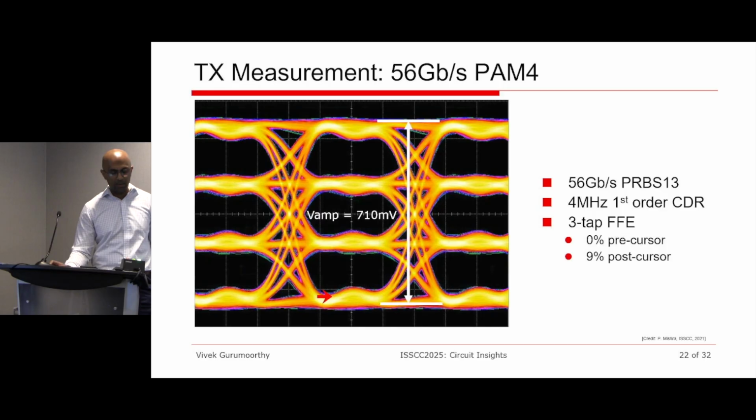So this is where the different levels come into the picture, right? So this is PAM4. So this is the -3, -1, +1, +3. And the way to visualize it is, let's say this is 710 millivolts, right? And you have 127 levels out of the 7-bit DAC. So if you just equally space them apart, so if this is 0 volts, that's level 0, and then you take the equally spaced level, which will be 127 over 3, which is 42, right? And that will be the 1/3 voltage here, plus another 42 is this voltage, and plus another 42 point something is this voltage. So that's all there is in this PAM4 transmission.